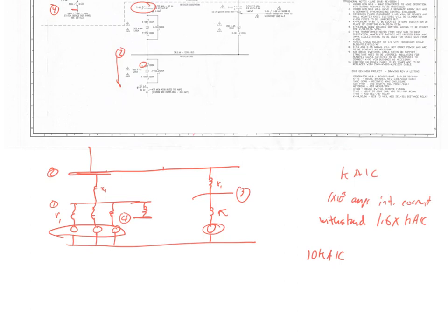You can have it connected or not, and the positive or negative sequence diagrams don't even care. That's a pretty important thing to help you understand sequence diagrams. You should highlight that in your notes. Why do I not care? Because it's perfectly balanced. They will always sum to zero. So whether there's a connection or not, the neutral connection sees no positive or negative sequence current. If you think about that, it'll help you understand where you're looking for your sequence diagrams and connections.